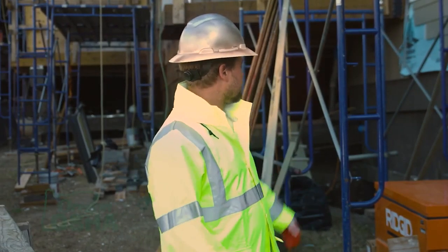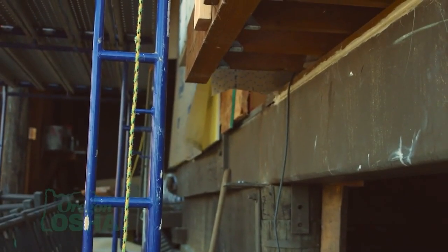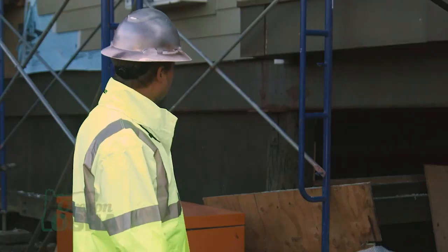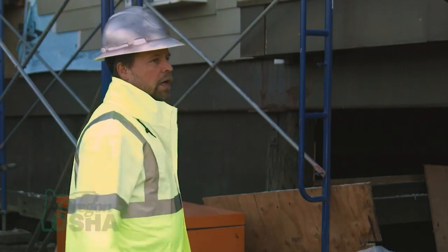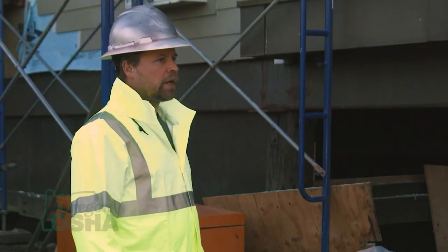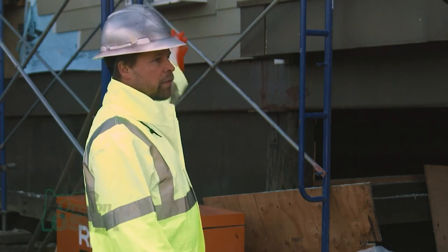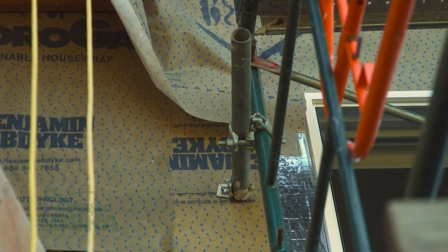Then, once we start building up, we want to make sure it's level. We choose the position where it's best, closest to the building, where we can work and set up properly. And start basically assembling. Obviously, it requires about 2-3 people, so one person holds it, another one adjusts it, so we make sure the right guys have proper training for that. And basically go all the way up. Once we get a couple of frames, a couple of levels, we want to make sure that it's properly attached to the building and keep going higher.